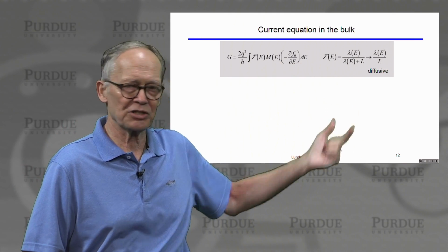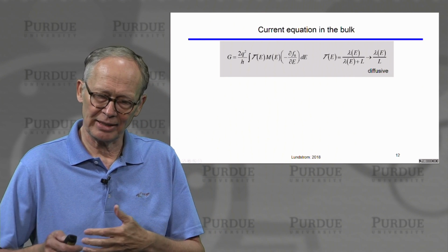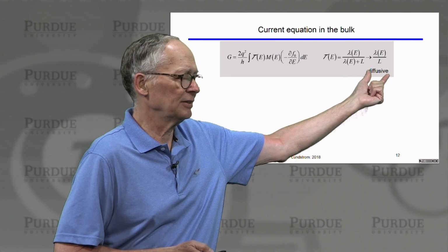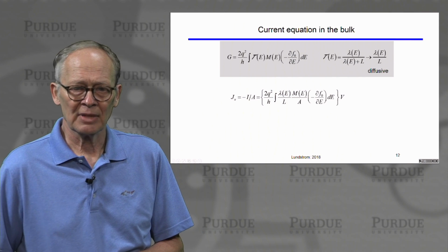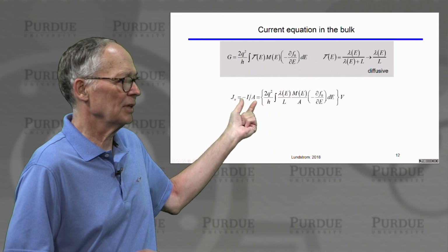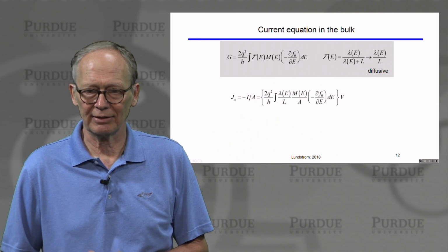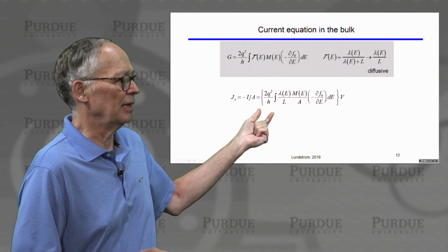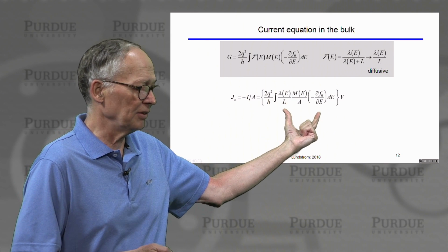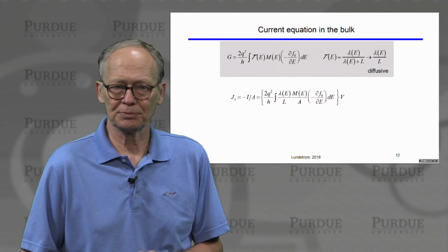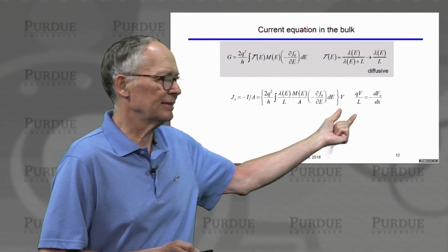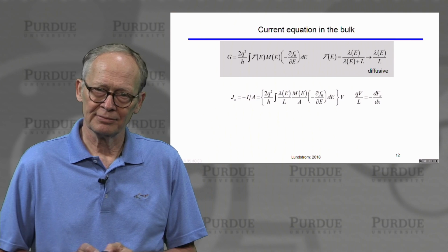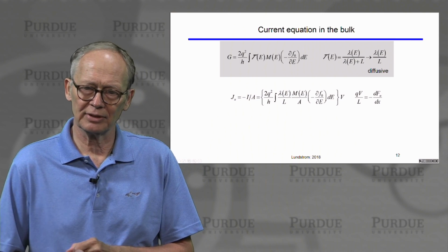Here's our transmission expression, but we have a semiconductor slab that is very long compared to a mean-free path, so it simplifies to the transmission in the diffusive limit. We're interested in the current density, which is current divided by cross-sectional area. When we do this calculation, we get a current given by this expression times voltage. But the voltage was producing a difference in Fermi levels. So Fermi level 1 and Fermi level 2 are different.